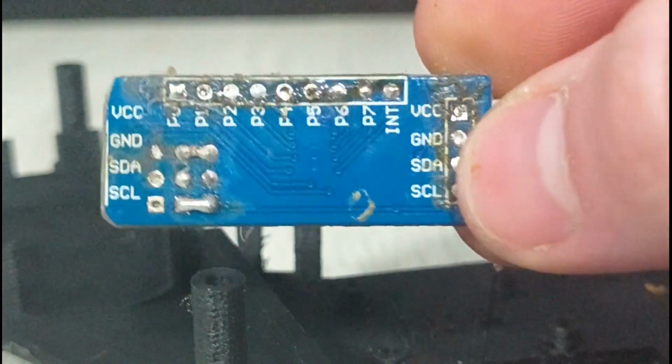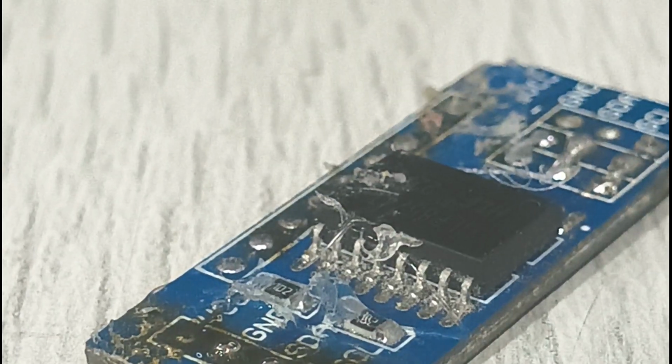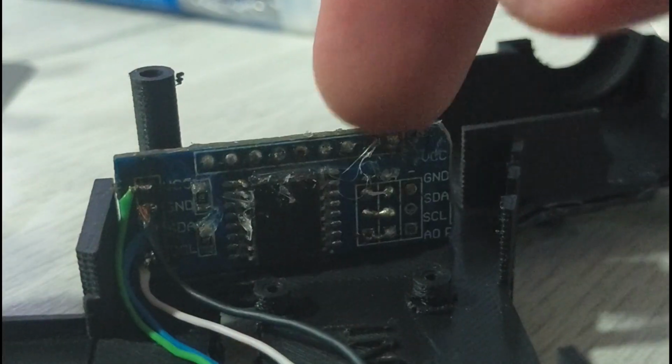Now you'll want to take a PCF8574 GPIO expander, trim it down, and add I2C wiring to it. You'll also set it to address 27 and remove everything else from the board so it'll fit. Then take that modified board and adhere it to the part of the frame that says PCA, and that's where the expander goes.